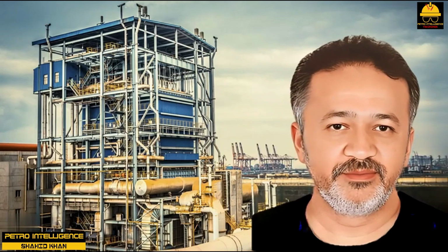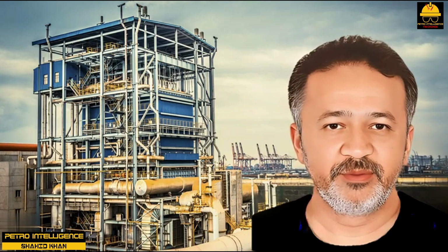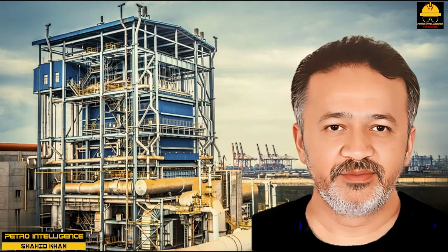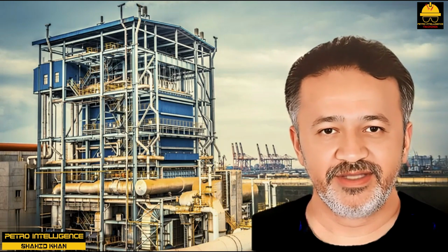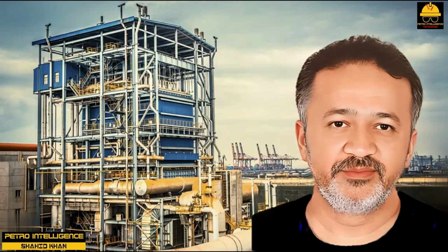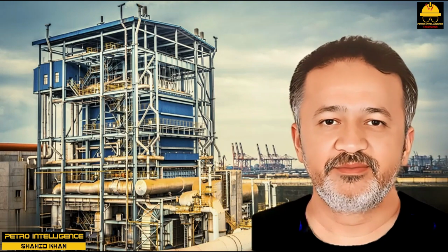Low-fin tubes. The low-fin tubes are made by machining grooves into the exterior surface of the tubes, which increases the surface area by 2.5 times. The use of low-fin tubes is not a new development. It is an idea that was in common use in the 1960s with mixed results. A successful application is the use of low-fin tubes in clean propane refrigerant condensing service, with clean cooling water on the tube side. Observed heat transfer rates increased by about 70%.